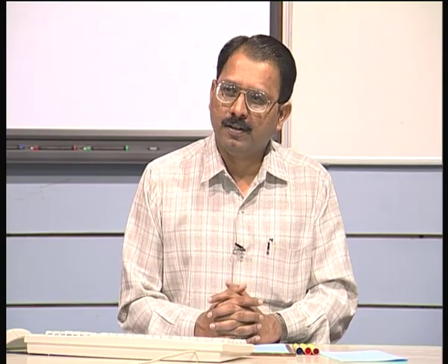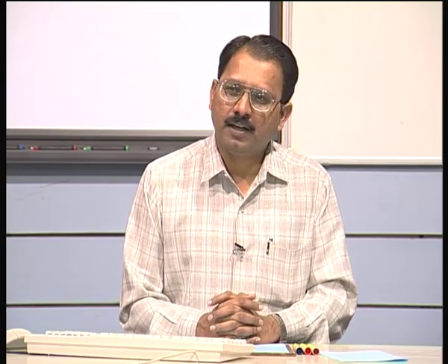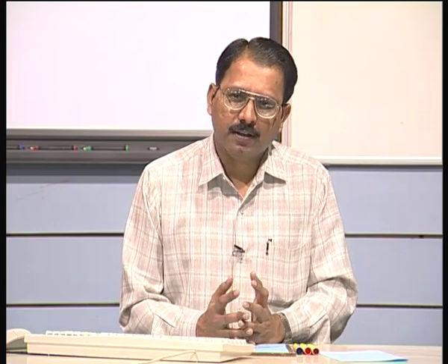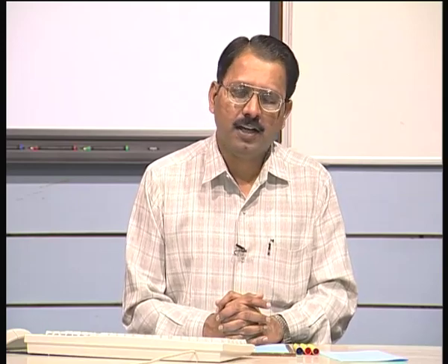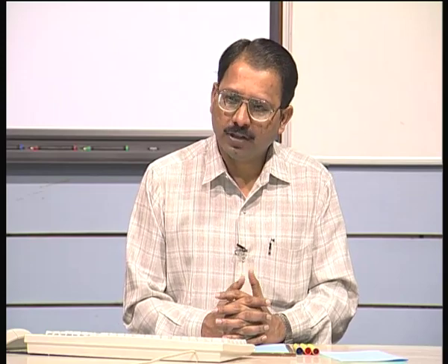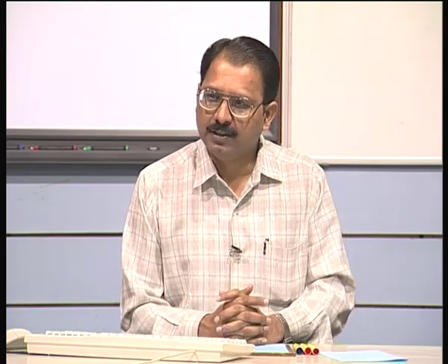Third, you are also looking at how easy it is to calculate certain volumetric properties from this particular object. That means, if I am doing some computational geometry related calculations, there may be other methods which may be convenient. So, one can say, and we will conclude later, that there is no universal or single representation which will give all conveniences. There are multiple ways of modeling solids, and one may choose to use more than one representation for a given application, depending on what you are trying to do with this solid model.